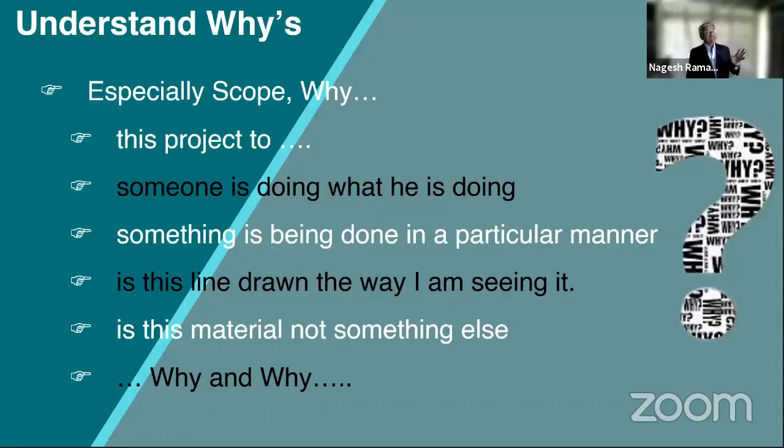So why is certain sequencing being done? Why are things being done in that manner? Why do I need a fire door? Why do I need this? Why should the staircase be so wide? Why should I have railings on the staircase on both sides? While there is a wall on the other side, why do I still need a railing? Why should the tread be 150? Why should the tread be 300, riser 150?